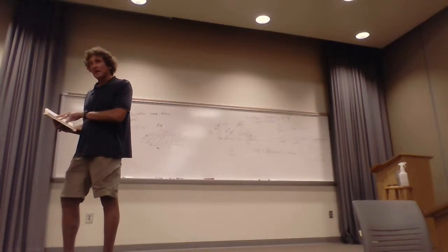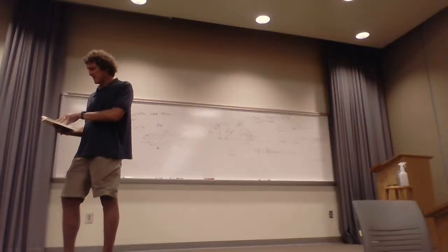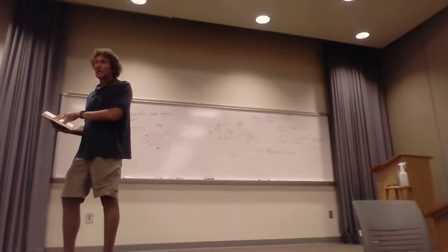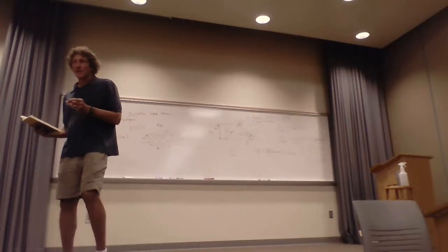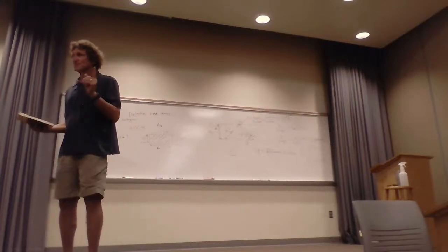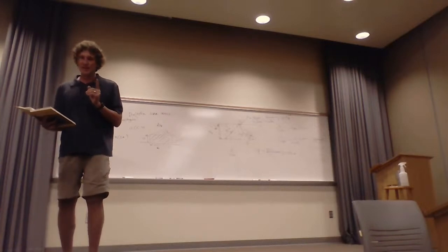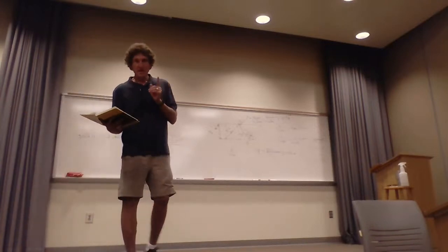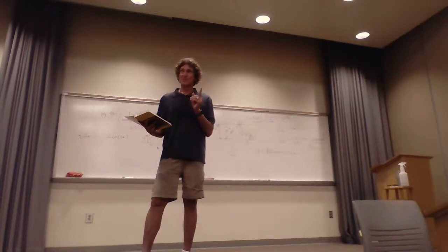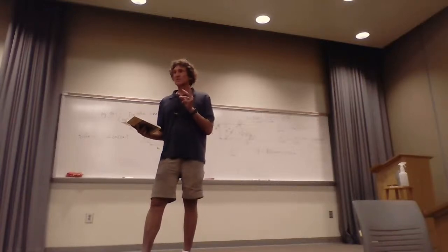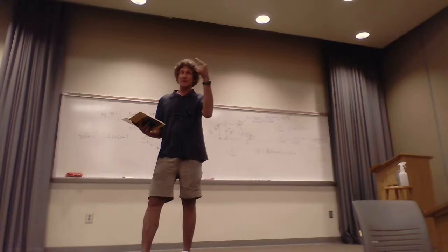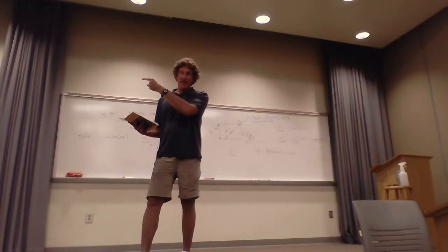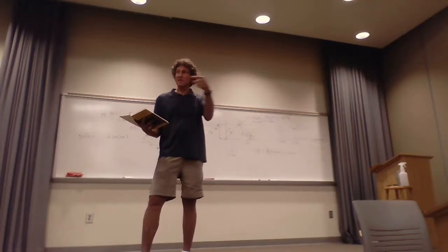Here's the one you circle and underline. On page 404, equation 7.95. It will show you the condition for only one mode to propagate. And who can tell me why only one mode is needed? Why do we want that? Why don't we want 2 modes or 3 modes? What do different modes tell you, really? Different angles of things ricocheting, right? And that means what? Different velocities of propagation.